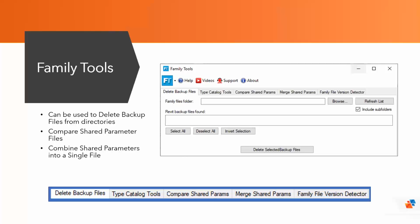I've seen shared parameter files with thousands of shared parameters inside of them, and then somewhere else on the server there'll be another shared parameter file that somebody else made, and no one knows exactly which one they're meant to be using. You don't know if they're exactly the same with some additions, or if they're completely different. So compare shared parameters, merge shared parameters, tools that are going to help you, and I wish I had them a few years ago, in order to take a look at those shared parameter files.